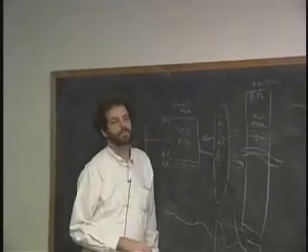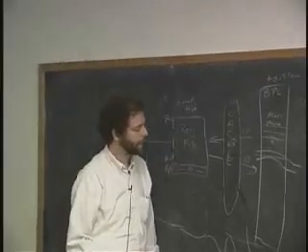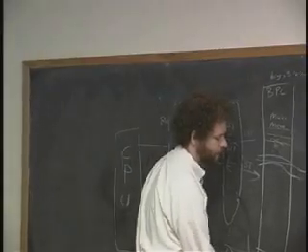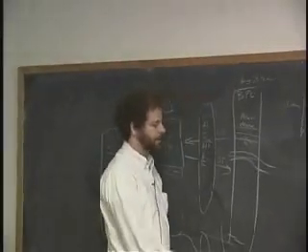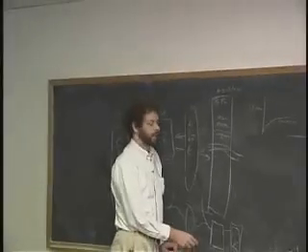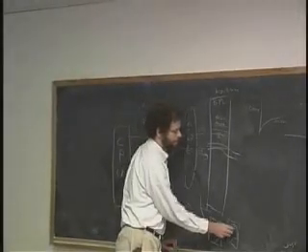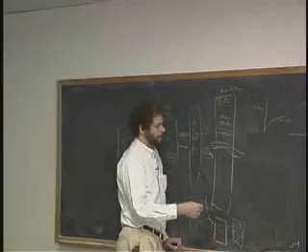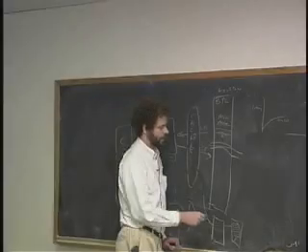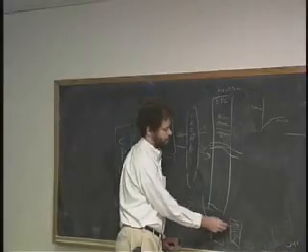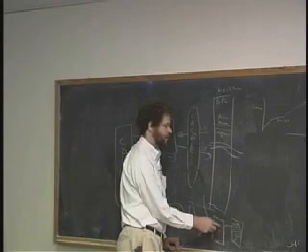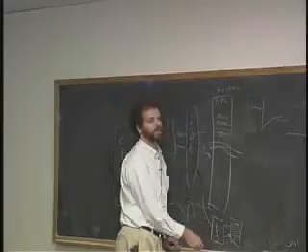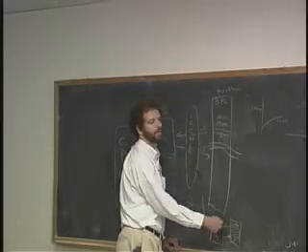Is VRAM intrinsically different from SDRAM? It is, and the reason is that on the other side of here is a screen, and the way that the screen works is that the screen forgets all the time. So there's a beam that scans over and over, and when it's done with one scan in 1/60th of a second or a little less than that, it goes back and it has to start all over. So constantly there's a stream of read requests coming into the VRAM here and data flowing back here. Incredibly high rate data going on this side.